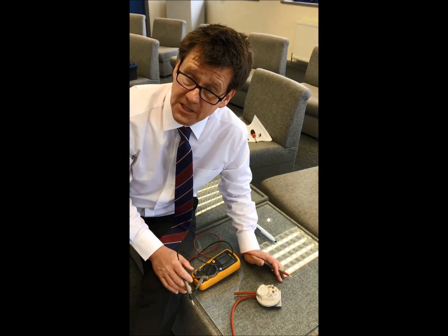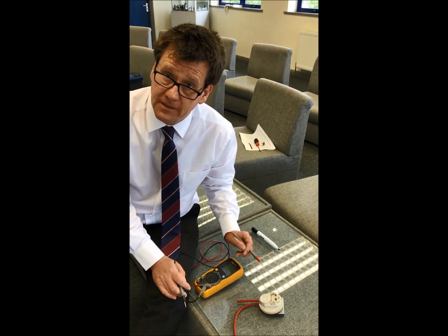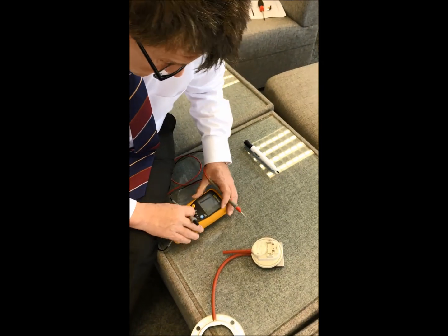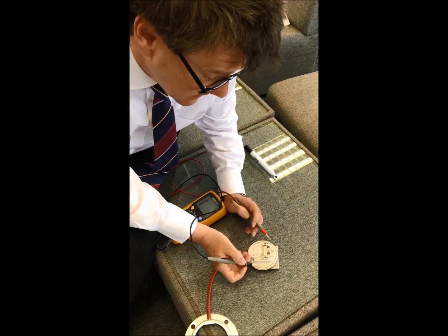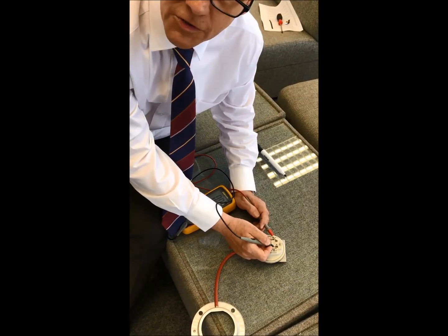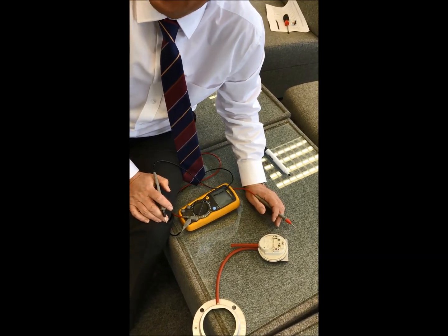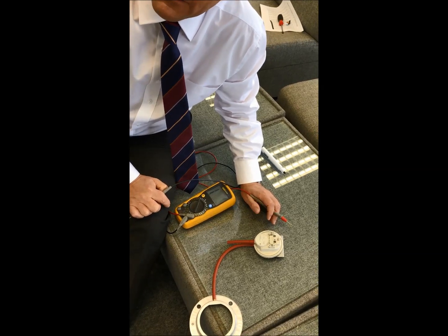Like we said yesterday, before you make yourself look a clown, just do a test outside before you take the air pressure switch in. If you just listen here, guys, I'm testing between common and normally closed. There I've got continuity. If I didn't have continuity between common and normally closed, bin it. Don't even bother fitting it in the boiler. It's up the spout. It's buggered.